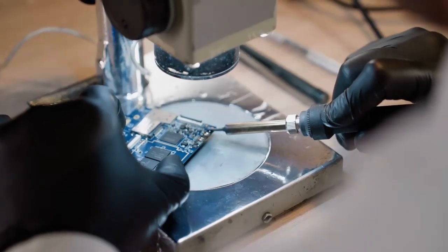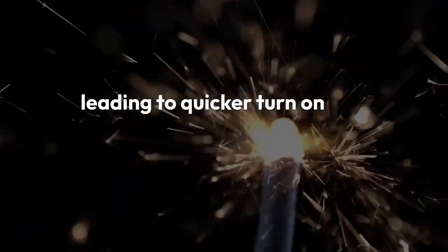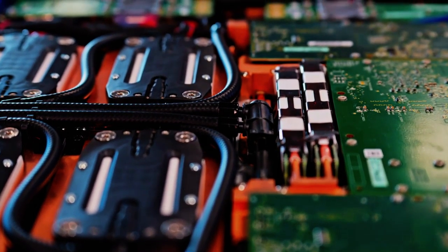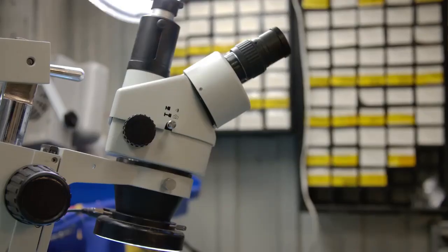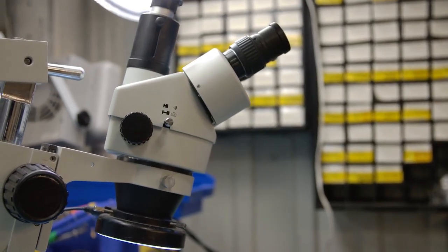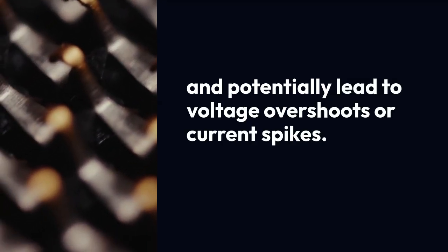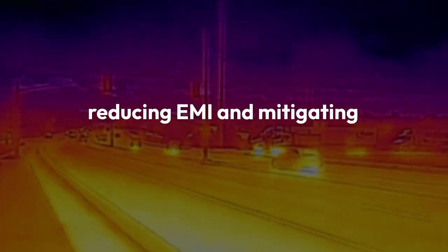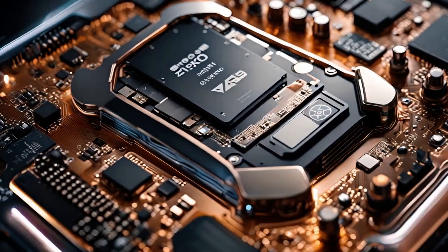A smaller gate resistor allows faster charging and discharging of the gate capacitance, leading to quicker turn-on and turn-off times for the power switch. While faster switching generally means lower switching losses in the MOSFET or IGBT, it also results in higher dV/dt and dI/dt rates, which can cause electromagnetic interference, EMI, issues and potentially lead to voltage overshoots or current spikes. Conversely, a larger gate resistor slows down switching, reducing EMI and mitigating voltage/current transients, but it increases switching losses in the power device.